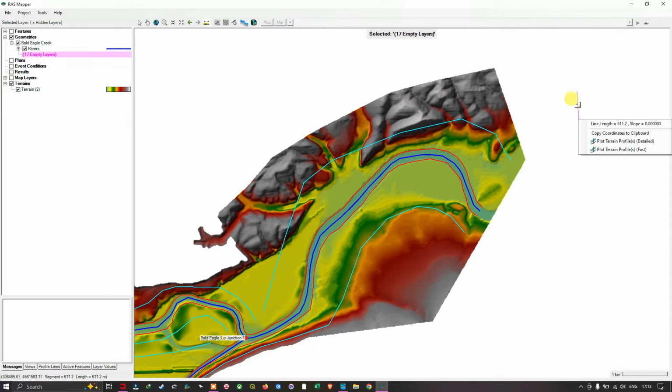So if you're gonna create a cross section here, right from the left to right, you have to create another cross section with a minimum distance of around half a kilometer. After a half a kilometer distance, you can create another line. You can see this particular measure tool here, it is around 594.3 meters. So I'm gonna create a cross section after every 500 meters of interval.